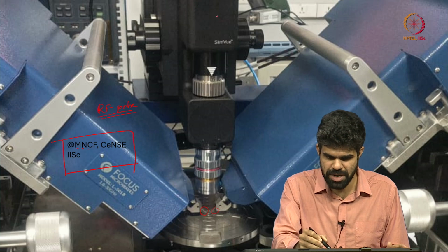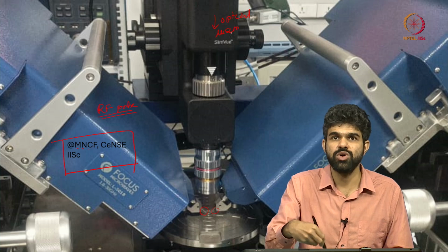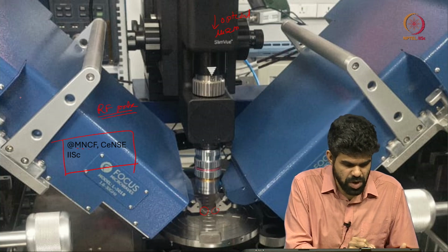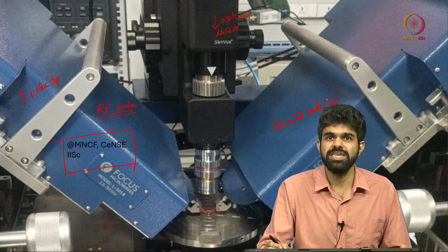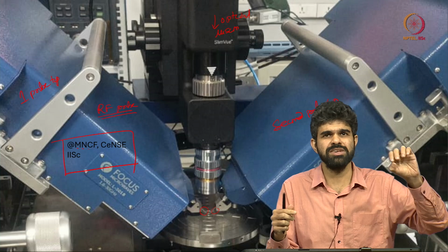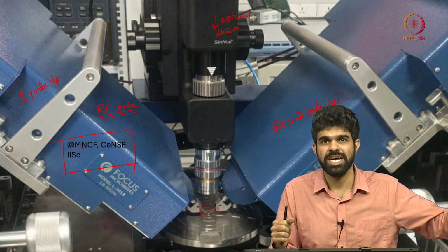This is the optical microscope to see your devices, right. Just one probe tip is this huge. This is one probe tip, and this is the second probe tip. Whereas in regular measurements I just use a small tungsten probe, which is shielded with what are called BNC cables or triaxial cables and so on.